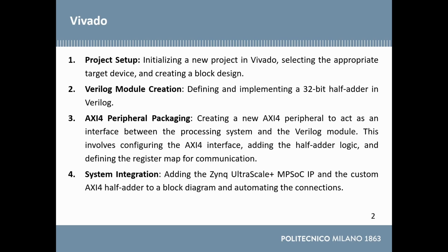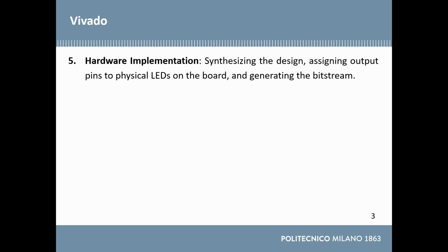System integration: adding the Zynq UltraScale MPSoC IP and the custom AXI4 half adder to a block diagram and automating the connections. Hardware implementation: synthesizing the design, assigning output pins to physical LEDs on the board, and generating the bitstream.